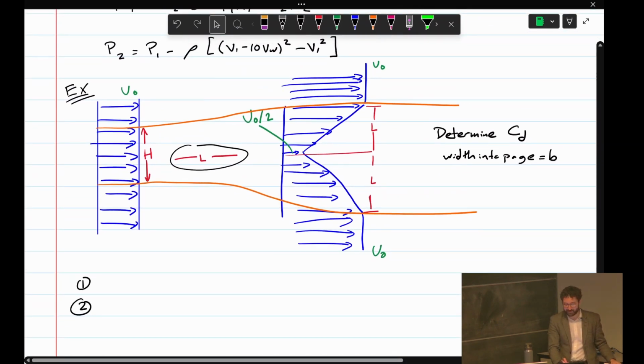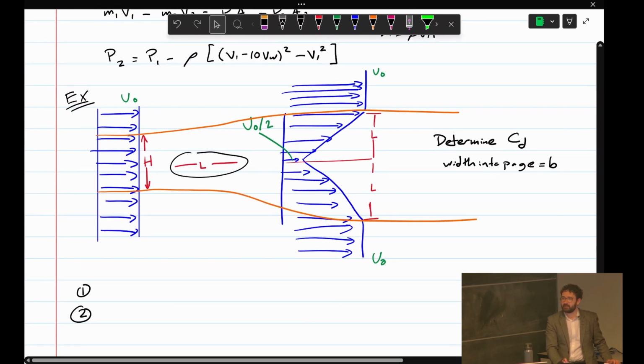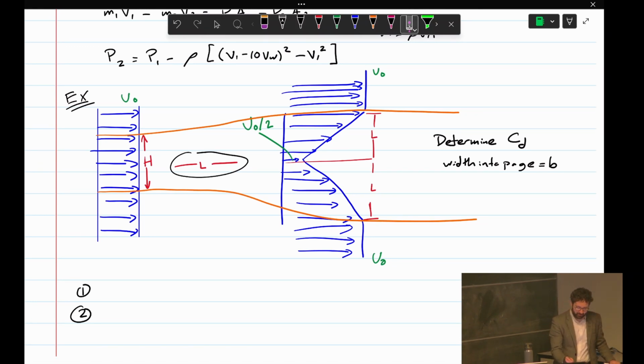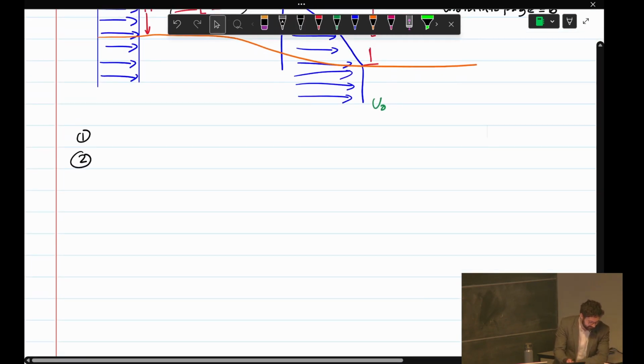Okay. So any questions on the problem setup or the solution procedure? The streamline thing is not something you'll have to come up with, so it'll look like this for any problem that you do. It's a streamline that we picture in our heads. We need to find out how big that h is in terms of mass conservation.